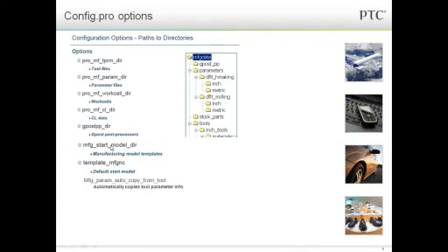And then also, if you do metric machining and English machining and machining for customer A and machining for customer B, and there's a lot of different scenarios that you could map to this idea, instead of you having to choose one every single time, you could put all of those different styles of start parts or different ways that you want to machine, and again, you can do a lot of different stuff with this. You can put them essentially into a folder, and as long as you uncheck that template button when you say file new, you would get a list of those, and then you would get a choice of the one that you want to use.